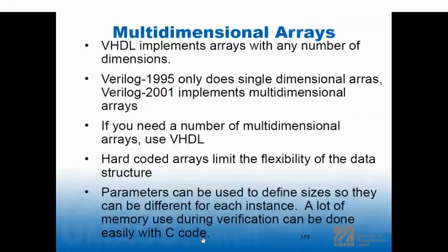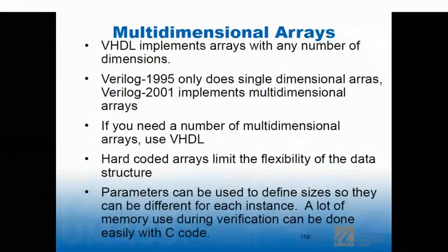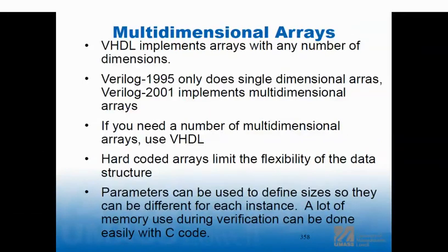Multi-dimensional arrays. So this is a verification class. We'll talk all we want about multi-dimensional arrays. Verilog supports multi-dimensional arrays. Isn't that nice of them? Guess what doesn't support multi-dimensional arrays? Hardware, right? RAMs are not multi-dimensional. So it's basically considered non-synthesizable to have a multi-dimensional array in a circuit. Now you might think, well, I wrote this multi-dimensional array and I synthesized it, it was fine. Well, maybe one of your dimensions was 0 to 3, right? It was only 4, and it put in 4 memories for you. But a true multi-dimensional array is not synthesizable.